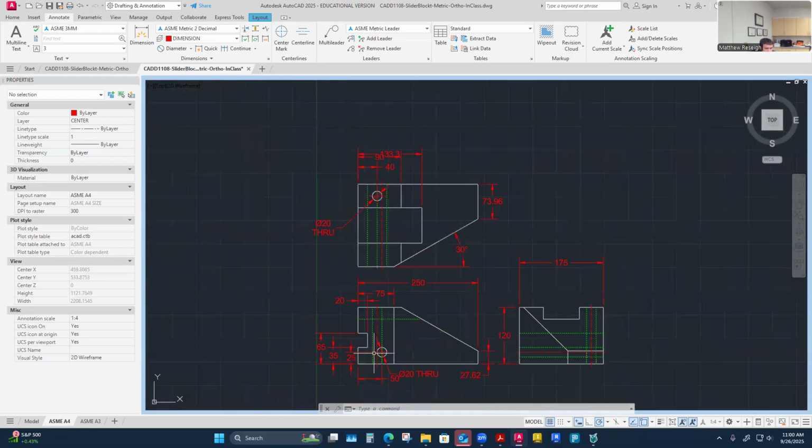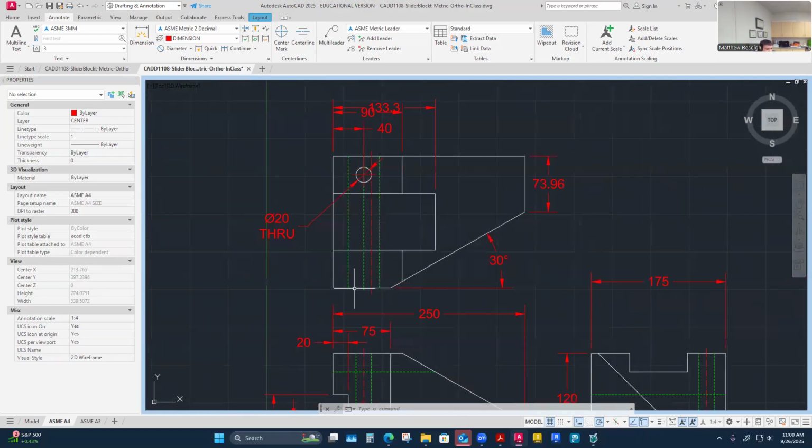And the argument would be, well, I don't know if I've pulled any dimensions from front, as I've definitely pulled left side and I've pulled dimensions off the bottom. I really haven't pulled any from the front. So really, to me, the better selection would obviously be maybe the smaller number, is what you would think. But really, I'm actually analyzing, because my argument here is if I pull from this to the center, now I'm establishing another datum kind of. Maybe I can just use what I've already got.